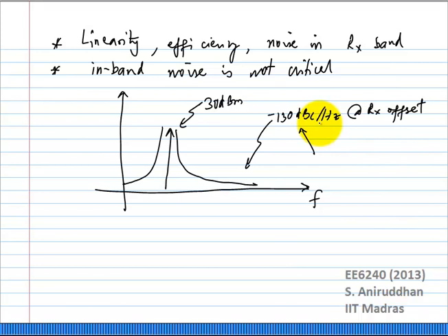However, you want to make sure that the signal to noise ratio is also preserved. It's not enough if it is just slightly lower. It needs to be much lower than the signal to noise ratio at the end of the receive chain, such that it doesn't degrade the signal to noise ratio. Or to put it in a different way, if the transmitter is outputting certain noise in the receive band, it will degrade the effective noise figure of the receiver by a certain amount.